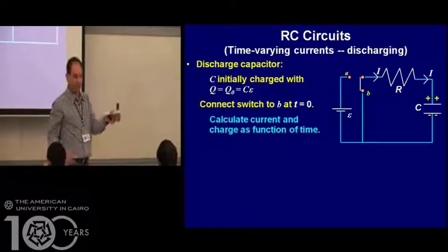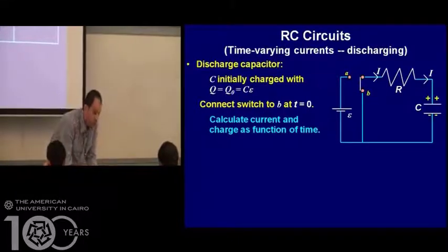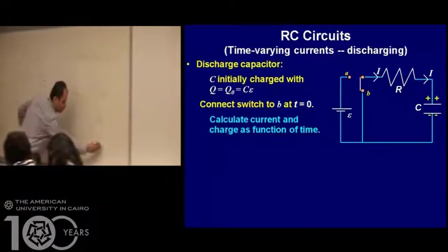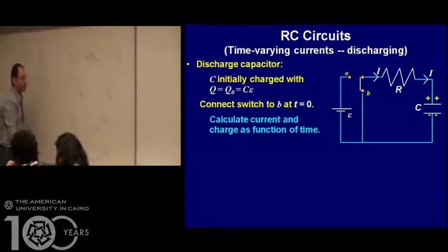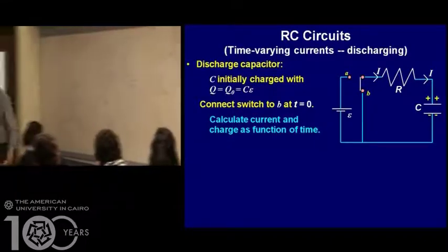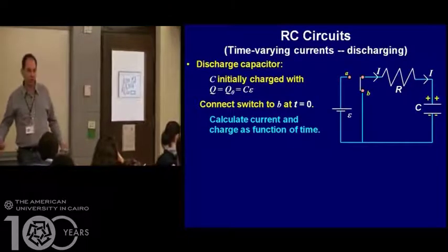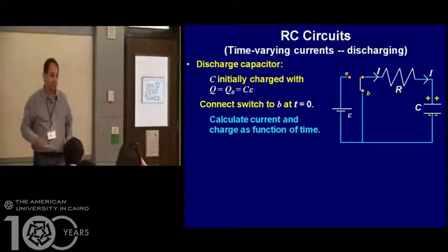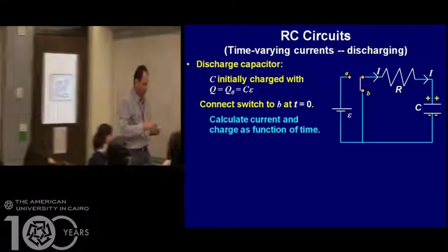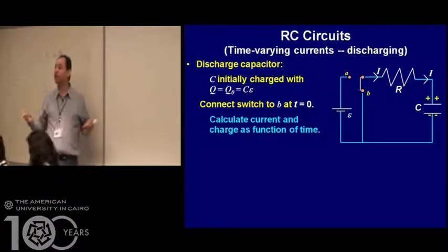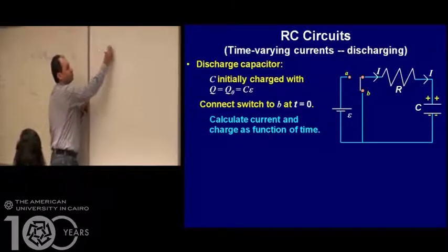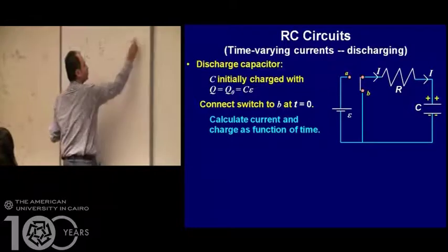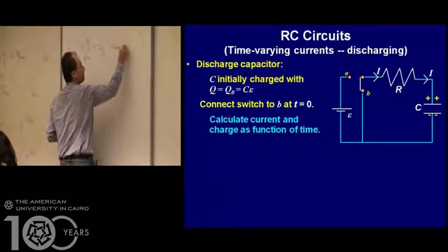It decays after time. Guys, before we move on, can you tell me what will be the current in the circuit? We need to describe not only the charge on the capacitor, but also the current in that circuit as a function of time. Hussein is saying, since the charge is a function of time, the current will equal dq over dt. So it's d by dt for the charge, which is q maximum e to the power minus t over RC.